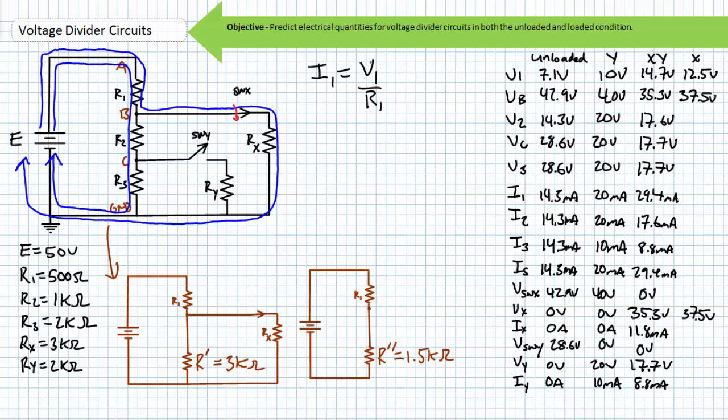Ohm's law suggests V1 divided by R1 equals I1. Substituting in the necessary values, we find I1 equals 25 milliamperes. Given I1 is the combination of bleeder current, the current internal to the original voltage divider, and current bound for load resistor Rx, we can say source current is also 25 milliamperes, and use either Ohm's law or the current divider rule to determine how the 25 milliamperes of current entering node B divides between R prime and load resistor Rx.